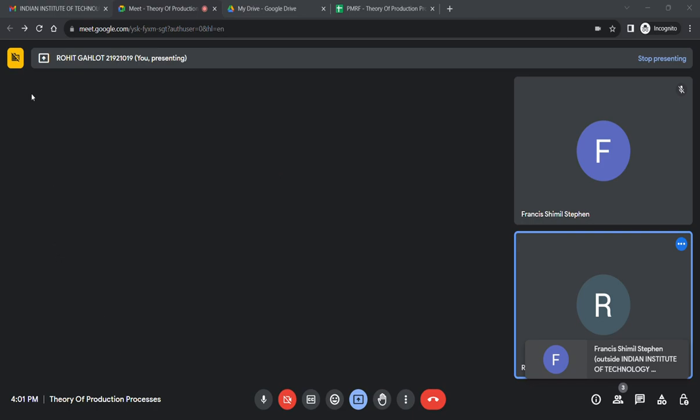I will be giving you the last problem to solve today. This fifth problem you will solve; till the fourth I will be solving, just to let you know how things are solved. So the third problem is this. Firstly we will calculate the volume of the slab, which is 30 times 20 times 5. Then, as we need to calculate the freezing ratio, firstly I will calculate the modulus of the casting.